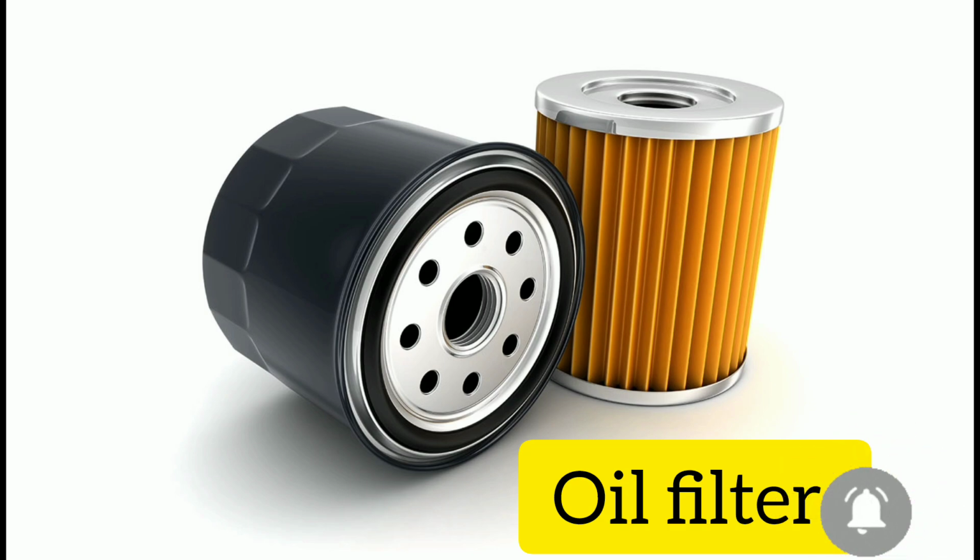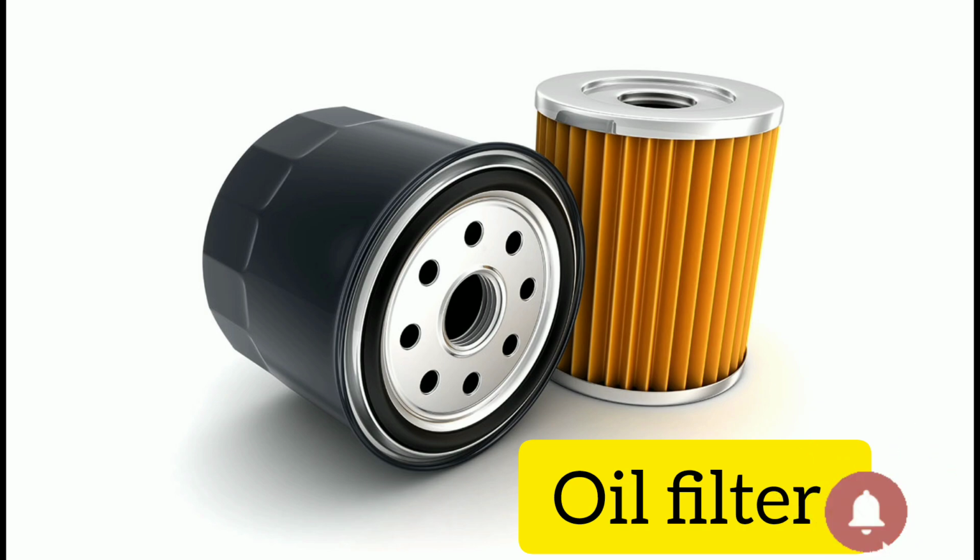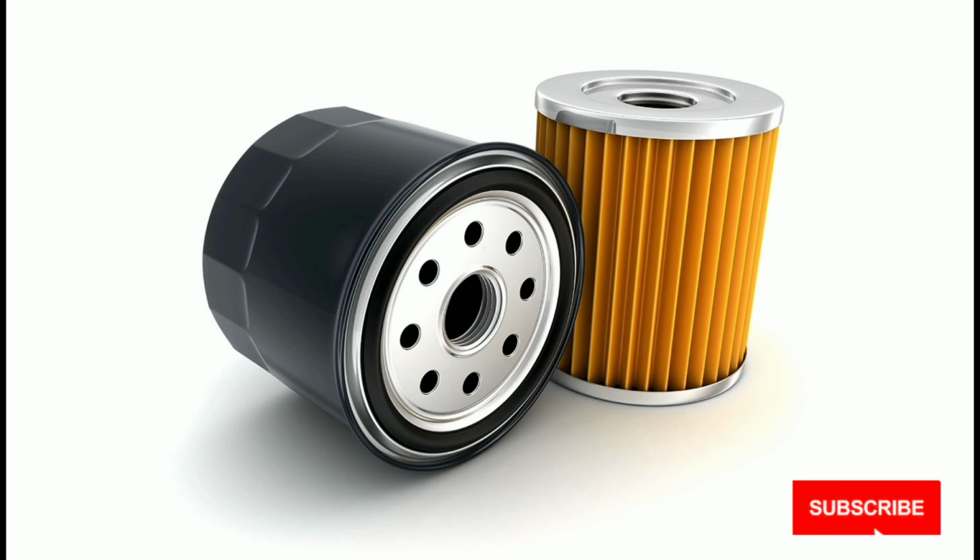This is an oil filter, and it's located on the cylinder block of an engine. Its purpose is to allow the internal moving parts of an engine to be lubricated with filtered oil. It removes the contaminants which could be in the oil, because as the moving parts of an engine move over one another, they create dust in the oil, and that is why an oil filter is there, to remove those contaminants and prevent them from reaching the engine's internal moving components.